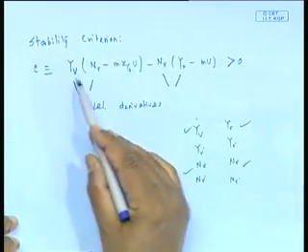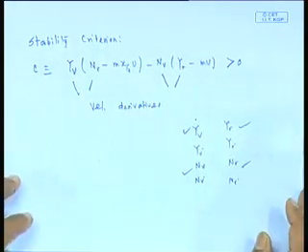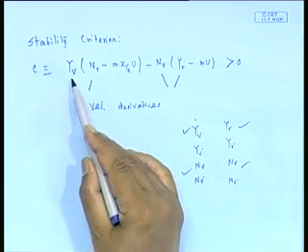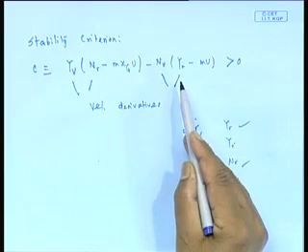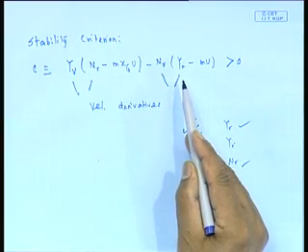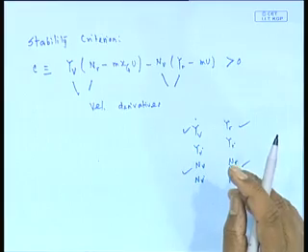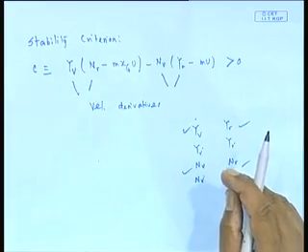Now this means that whether the hull is directionally stable will depend on the values of YV, NV, YR, NR. This is of course with dimension. I will go right now to the usual form of non-dimensionalization, because typically we write this in a non-dimensionalized form. I did not say that so far because it does not change the conclusion.